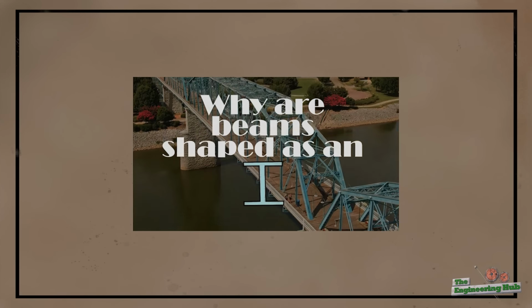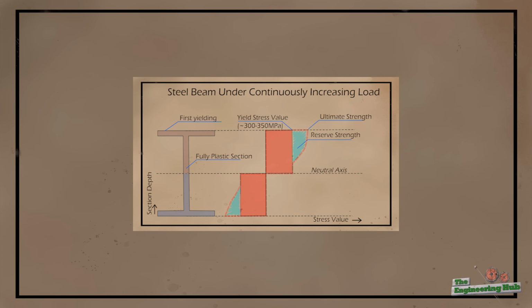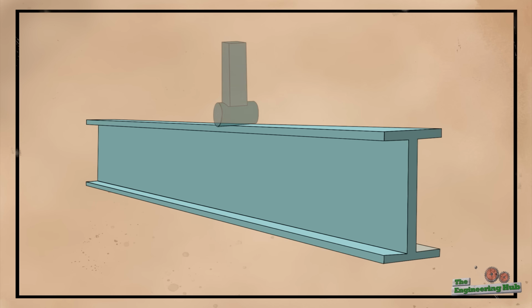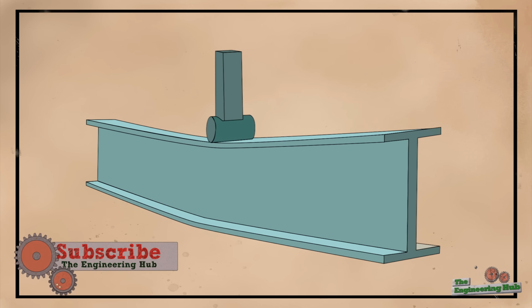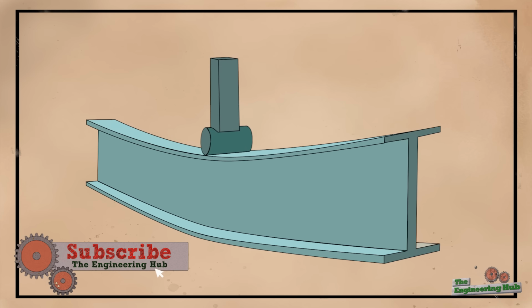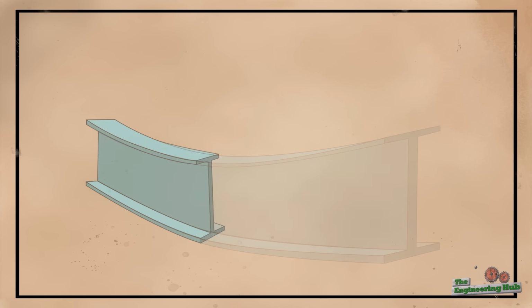In a previous video, we reviewed the secret of the I-beam's strength. Click here for a refresher on that. To summarize, the I-beam's strength comes from having more area further from the center. This makes the shape very strong in bending, which means it can take lots of downwards loads.